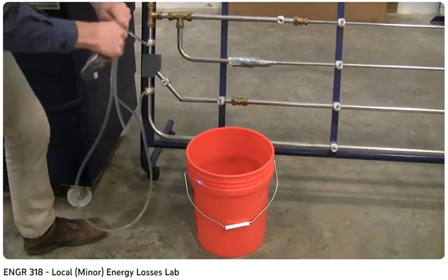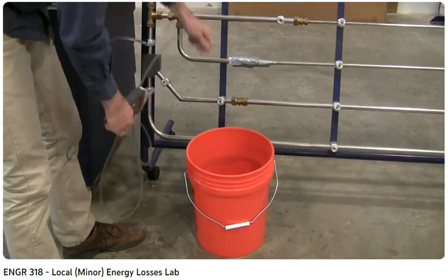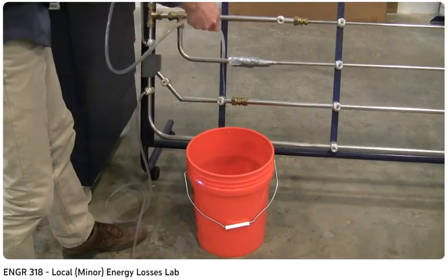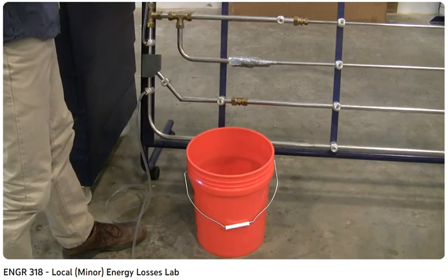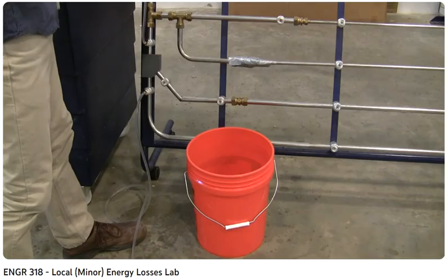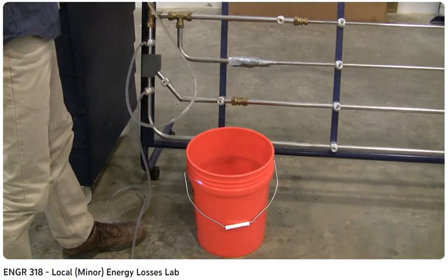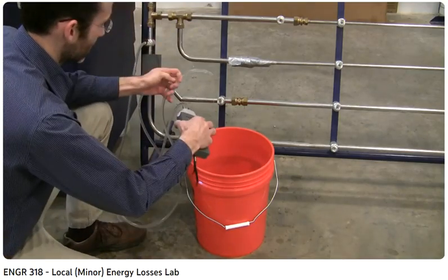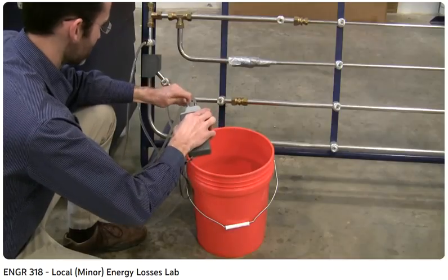these lines of air. All you have to do is disconnect it from the pressure meter, and water will flow into the bucket. I'm going to raise it up to try and coax those air bubbles out of the tube. I can see there's actually a pretty long stretch of air in there. This will really improve our accuracy considerably, to make sure that there's nothing but liquid in there. And I can just plug it back in and it's good.